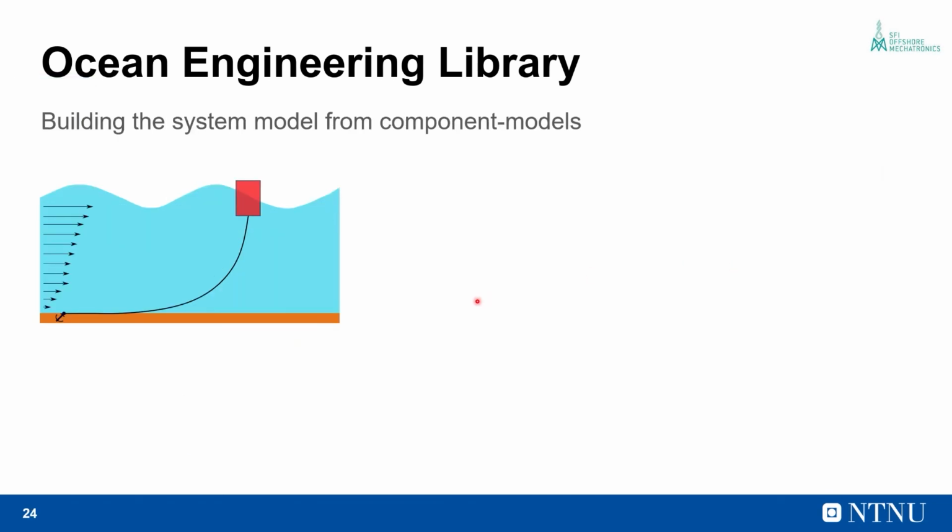And so we now have developed component models for the waves, the currents, for fluid loads on the buoy, as well as component models for the mooring loads.